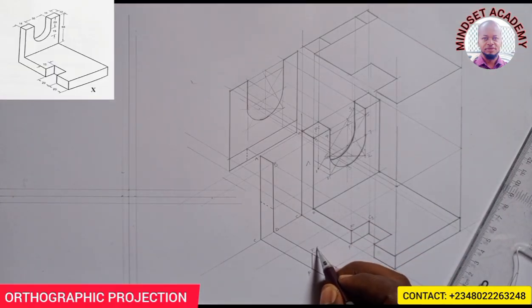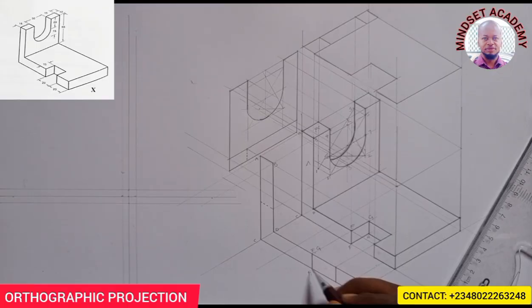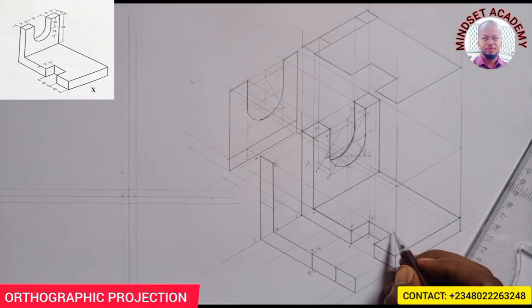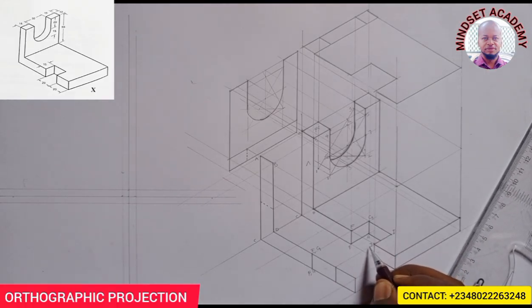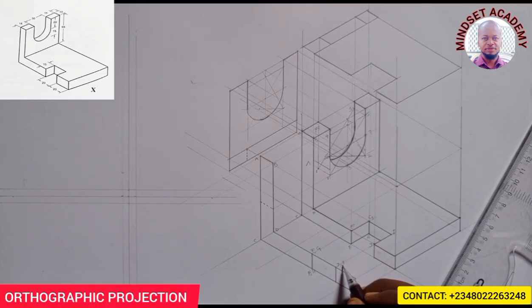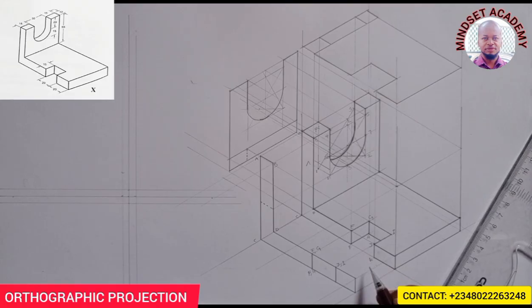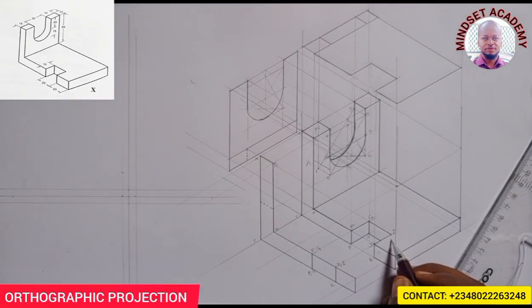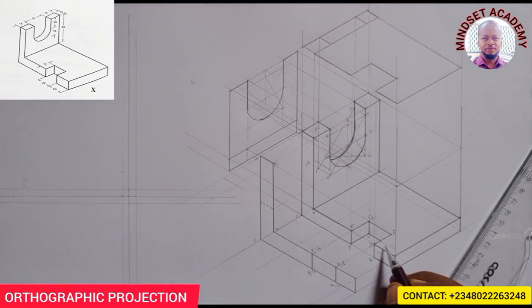So E and G will be on the same point. Let's call it H. H and F will be on the same point, right? Let's call it J or I. This is I and this is J. So J and I will be at the same point. Let's call here K. But there's another one here that we are not seeing that is joining here like this. That point will be L. So K and L are on the same point, just behind it, a hidden line here.